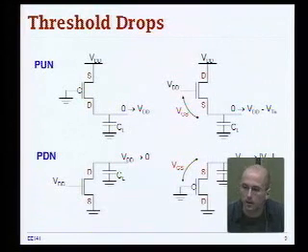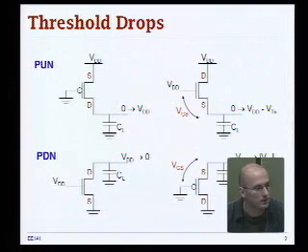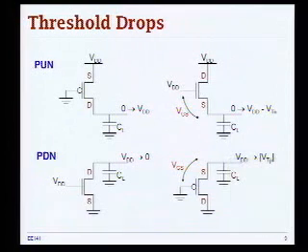But then the problem with this would be what will happen to the propagation delay of the next stage if you have reduced swing? It keeps increasing, right? Because you don't have sufficient drive strength to strongly turn on the transistors in the next stage, and therefore it's sort of a trade-off. You can have lower power, but you have to pay a penalty in performance.